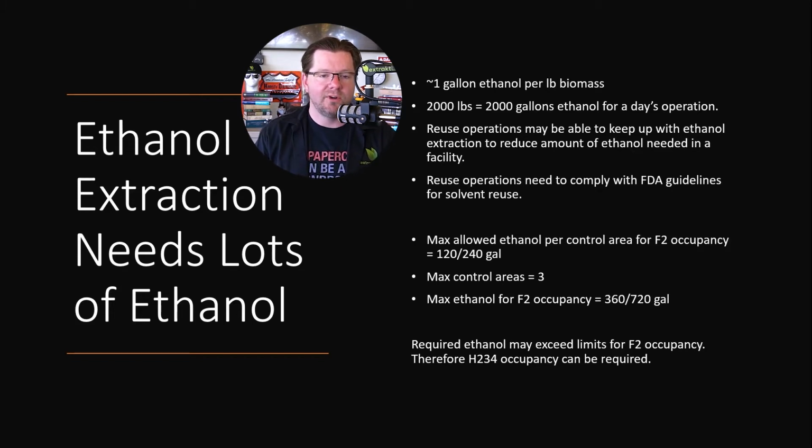Certainly, reuse operations or using falling film, for example, may be able to keep up with the ethanol extraction to reduce the amount of ethanol needed in a facility. Reduce and reuse operations, or recycling operations, need to comply with the FDA guidelines for solvent reuse. This includes specifications back to its original state, testing, and validation. I'm not going to talk about that here, but it's a part of the operating costs that you need to be thinking about when you anticipate reusing solvents.